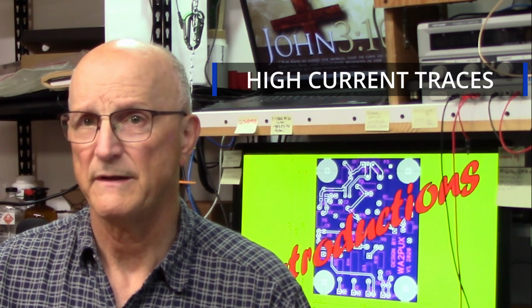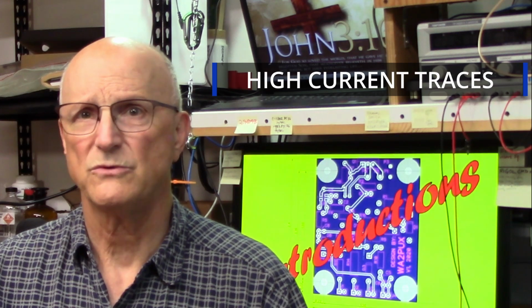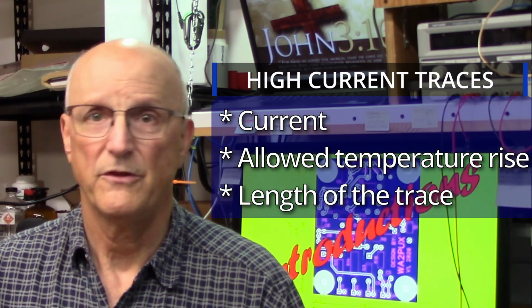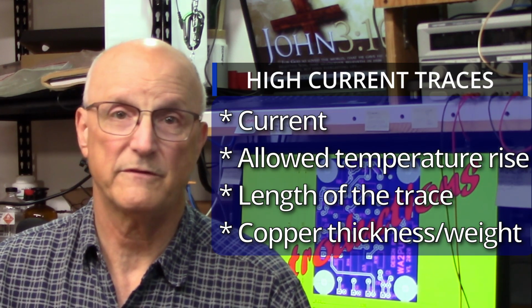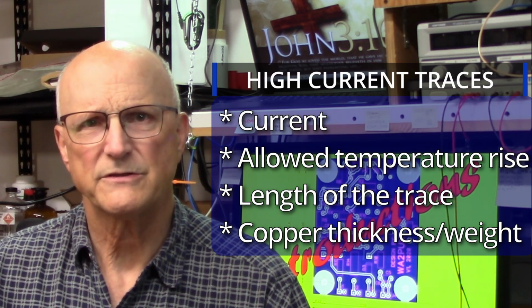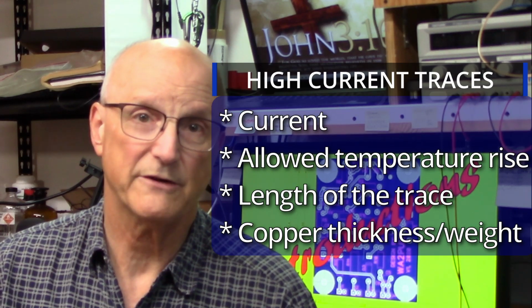If your trace is going to be carrying any kind of current, then the trace width has to be increased accordingly. The actual needed width depends on the current to be carried, the allowed temperature rise of the trace, the overall length of the trace, and the copper weight of the board, such as 1 ounce copper versus 2 ounce copper. And there are online calculators available to determine this number for you. I've put a link to one such calculator in the description for you.